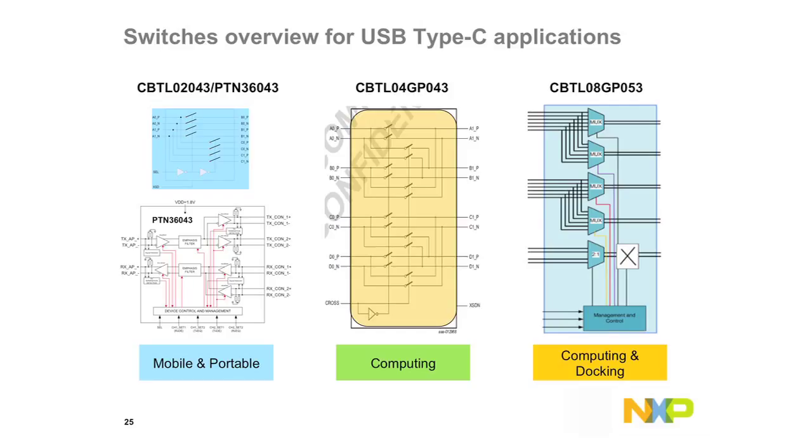Again, if you remember the pinout, we had 2 sets of differential channels on each side. So through one, you will send your USB 3 TX-RX. Through the other, you can send, say, 2 lanes of DisplayPort, which can still do quite a bit of resolution. And now when you flip the plug, your DP lanes are going to get swapped, and your USB lanes are going to get swapped too, right? So essentially, you need a crossbar switch. So that's what those switches are, depending on your application. How many lane crossbar switch do you need? Do you need a 4-lane crossbar or a 6-lane crossbar? Okay.